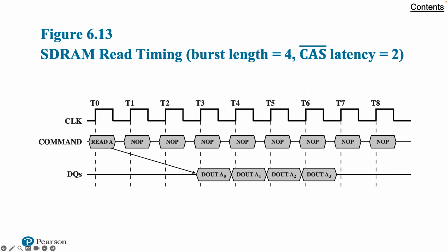represented by binary 0. A signal transitioning from 0 to 1 is frequently referred to as the signal's leading edge, and transition from 1 to 0 is referred to as a trailing edge. Such transitions are not instantaneous, but this transition time is usually small compared with the duration of a signal level. For clarity, the transition is usually depicted as an angled line that exaggerates the relative time the transition takes. And so we're seeing this here. This is where you have those transitions going on.